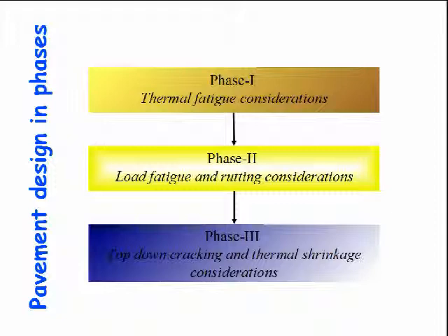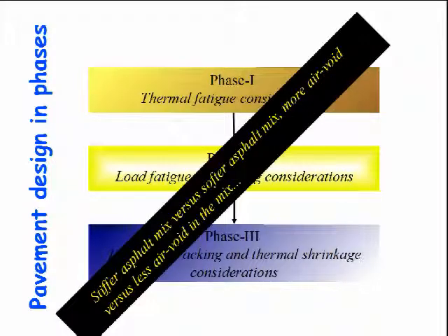And if so, as I have shown you in the previous slide, or the slide previous to that, the question is whether all these 5 distress modes are connected in series and parallel. And now I place the argument that if they are not dependent on the thickness, then I can keep them aside and I can do a phase 1 and phase 3 check. But then in phase 2, we have to think once again about fatigue and rutting as we did earlier. Of course, the issue remains of the integration of the mix issues and the structural thickness issue, and sometimes they are conflicting. For example, you need to have a very high stiffness, because if you have high stiffness, then your stress and strain values will be low.